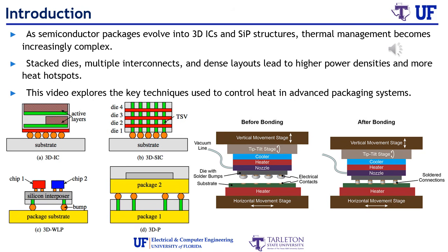As electronic devices advance, they pack more transistors, run at higher speeds, and shrink in size. All of that concentrates power into a tiny volume, and almost all electrical power eventually becomes heat. Without careful thermal design, temperatures rise quickly. Excess heat slows down transistors, shifts timing, and accelerates reliability problems like electromigration, delamination, and mechanical stress. In extreme cases, hotspots can cause permanent damage or failure.